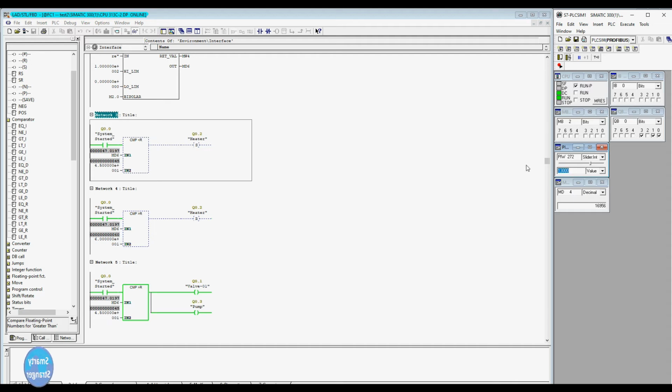We see that at 45 centigrade the valve will close, the pump off and the heater start again. When the temperature goes back to more than 45 centigrade, the heater starts and also the valve will open and the pump start running. You see guys how simple is this?